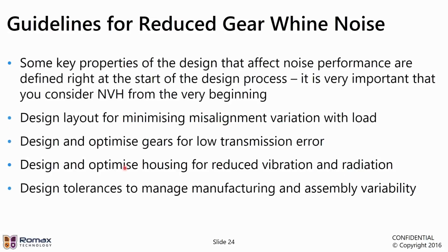So we're going to talk now about some guidelines for reduced gear whine noise and designing quiet transmissions. As I said, this really is just an overview, but this should give you some really useful little tips to consider. And of course, the first thing is that we know some key properties of design that are affecting the NVH performance are some of those things that we have to define right at the very beginning, even to get down to things like tooth numbers on gears and module and types of bearing and that kind of thing. So for that reason, it's very important that you consider NVH and gear whine right from the very start, because that is when the biggest impacts can be made.